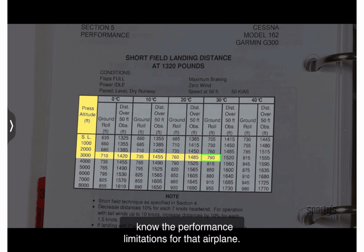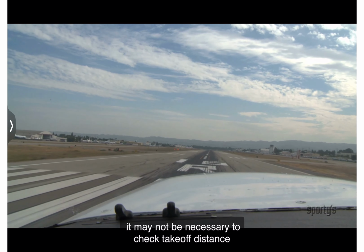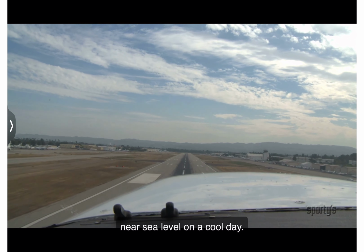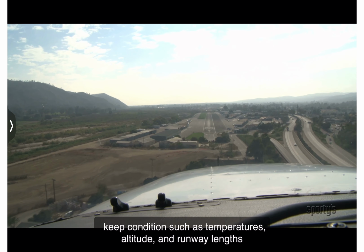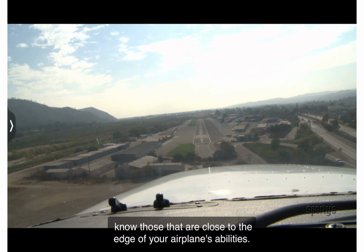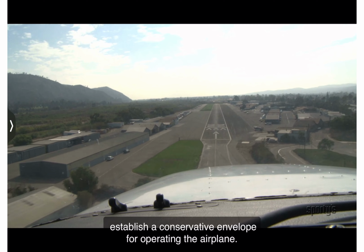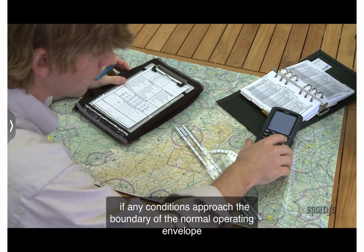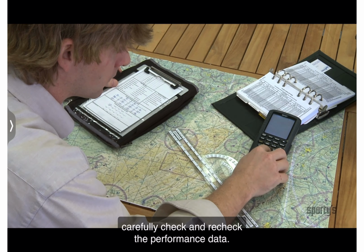Know the performance limitations for that airplane. It may not be necessary to check takeoff distance when taking off from 8,000 feet of runway on an airport near sea level on a cool day. Keep conditions such as temperatures, altitude, and runway lengths in the back of your mind. Know those that are close to the edge of your airplane's abilities. Establish a conservative envelope for operating the airplane. If any conditions approach the boundary of the normal operating envelope, carefully check and recheck the performance data.